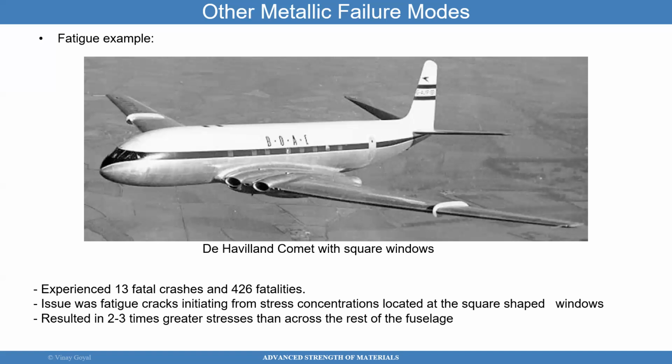Well, on the ground, the delta pressure across the fuselage is zero. But when you go to 40,000 feet altitude, you have to pressurize the cabin. Otherwise, the people inside are not going to be very comfortable, right? And the outside pressure has dropped because the altitude is higher. So that causes a delta pressure across the fuselage of about 9 to 10 psi, and that's stressing the fuselage, right?